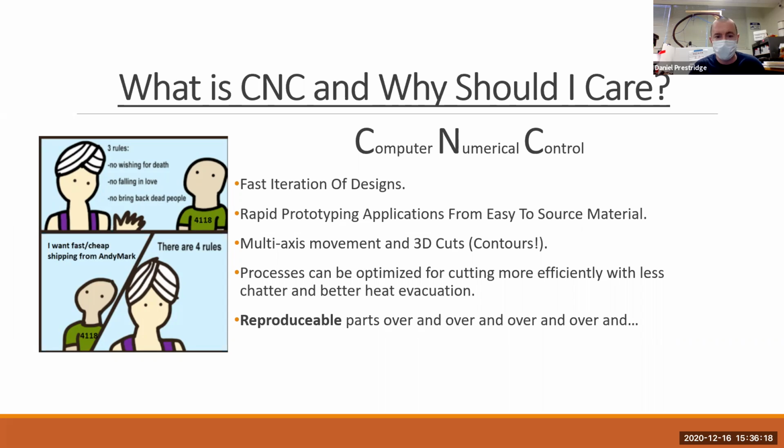So it's pretty amazing. And the process can actually be optimized going through some of the paths included in Fusion 360 and some of the other stuff that I'm going to mention later. It's actually smart enough to realize, hey, this might be more effective if I move to a different spot, let that side cool down a little bit, come back and do this other process. You'll have better results because you don't have so much heat buildup, and you'll have more reproducible, accurate, and an overall better product if you use some of these. However, some of them can be time consuming, and you kind of have to make that trade-off between the two.